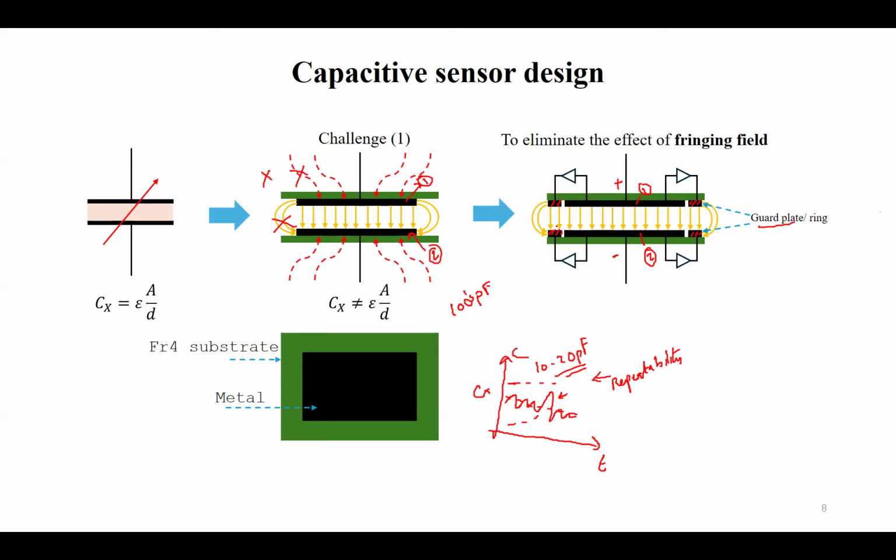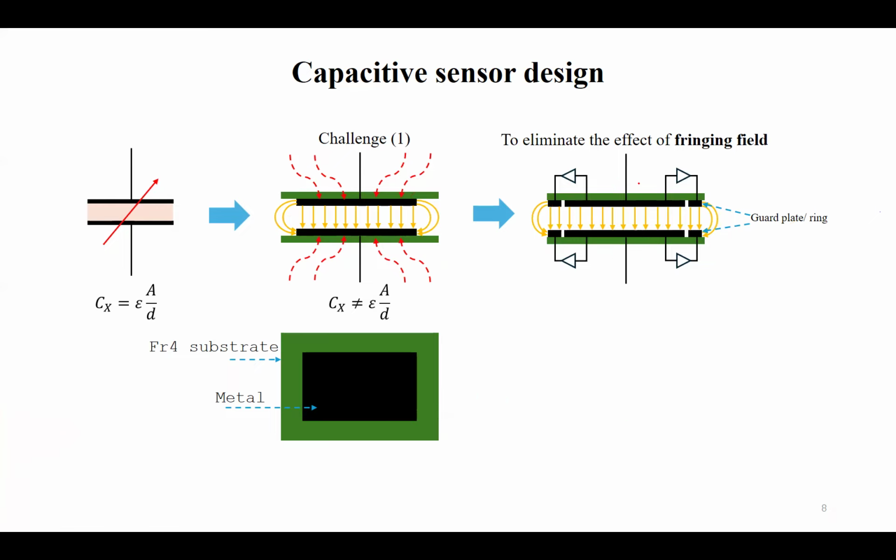These plates are called guard plates or ring plates. So we'll connect the same voltage to the guard plate. Okay, so let me just erase this. We have applied the same potential here, plus minus, plus minus. So from this point to this point, we will get electric fields which are perpendicular to the surface, and only at the ends are fringing fields, which are not required.